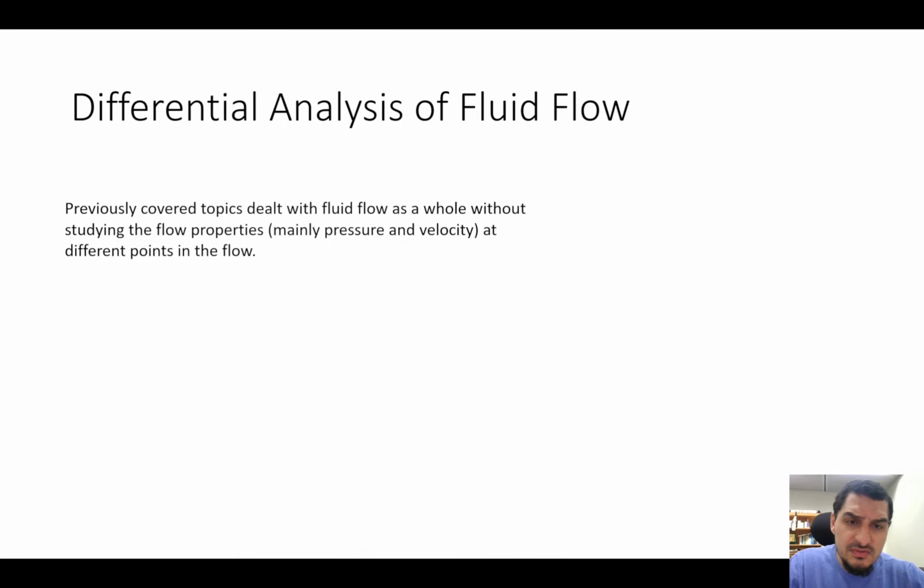And we said that the average velocity can be a good approximation that will express the whole fluid in the whole pipe or tube. And this was very useful, and it was a very good approximation that we used to calculate what we wanted to calculate, whether the pressure drop, the velocity, or whatever, in an easy and straightforward way.